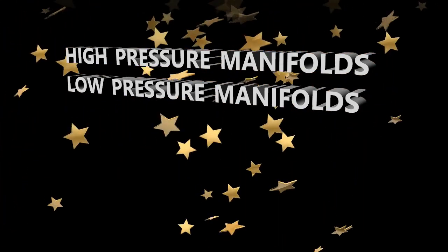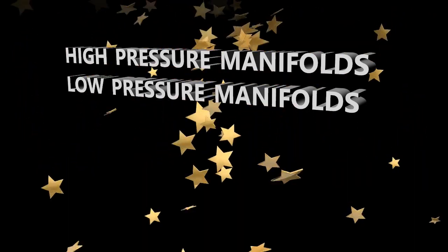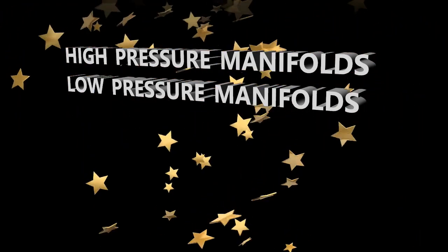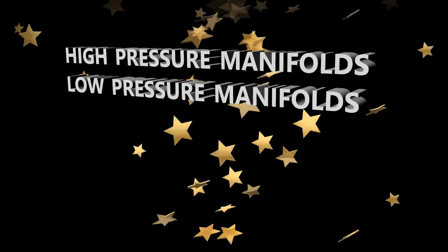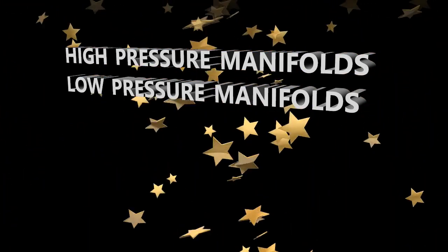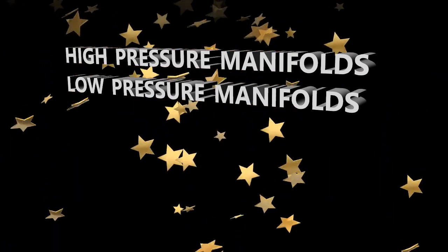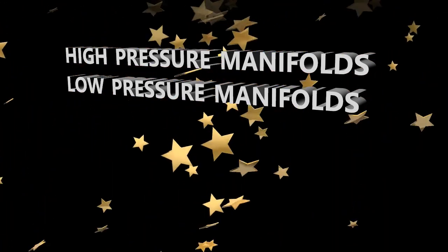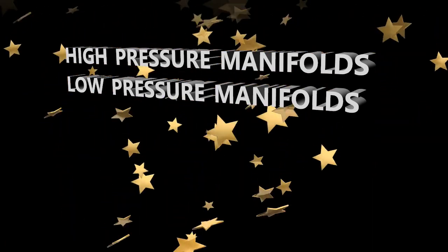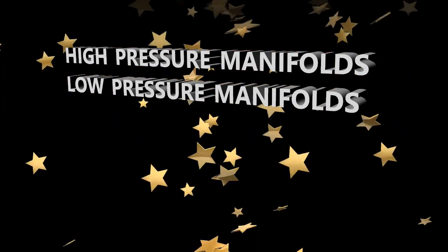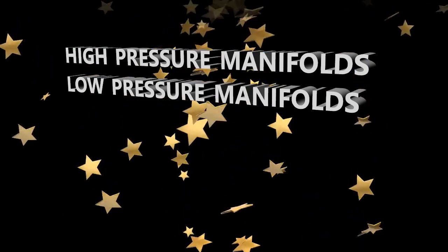All right, so your pressure relief valve is a two-stage valve. You've got a primary and you've got a poppet valve. And again, like I mentioned before about those opening and closing thresholds, 237 bar or 3,436 psi is when it opens, when that pressure gets to be a little too high.